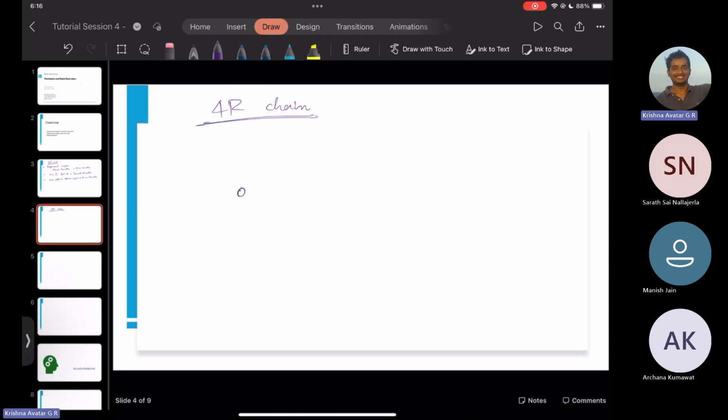It's essentially a construction of 4 links connected by 4 revolute joints, one of which is fixed, which we call the ground. So this is ground link 1, this is link 2, link 3, and link 4. These are all revolute joints, so we have 4R, and that's the reason we call it 4R. Given some input, we determine some output, which as per the notations is theta 4. So given theta 2, determine theta 4.